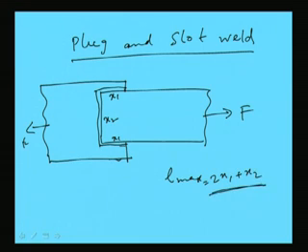So, with a particular load, sometimes the required length becomes more than this 2x1 plus x2. So, in that case, how to accommodate it? That means, the welding length whatever it is, 2x1 plus x2, how to accommodate more than this length. So, this can be accommodated through some plug, through the introduction of plug and slot weld. How? We are cutting some portion and making like this. That means, welding is done through this area and again through this, just to increase the area of welding, increase the length of welding. So, what we are using is called plug or slot weld, right.